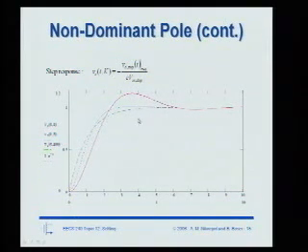And you know, you could play with this and see that 1 is probably too little, but if I make it a little bit larger, so here this is the case of 3. Interestingly enough, it almost looks like the case with 3 is settling faster, right? It's actually almost overshooting, but not quite, and reaching some tolerance. It looks like it's actually reaching a given tolerance spec faster than a single pole system.